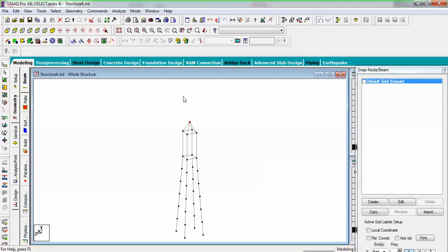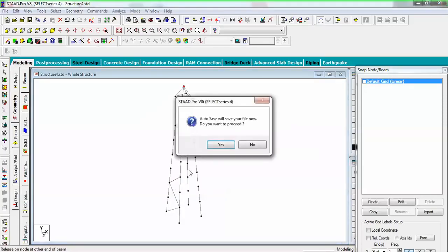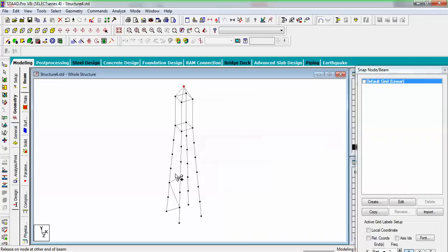Now the tricky part is that we have to add bracings onto these legs. For that, orient it by isometric and go with add beams. There is one trick, you have to go exactly like this: first one, then you have to leave this one. So select this one, this one. Now leave this one and connect like so.